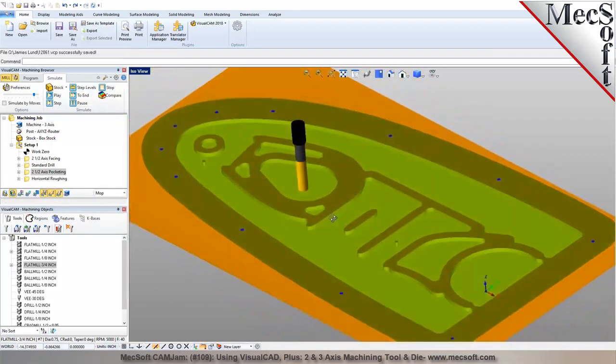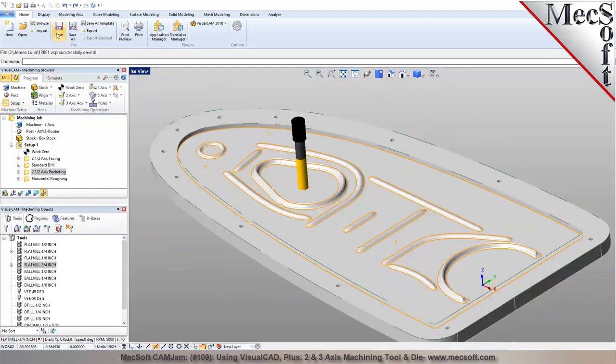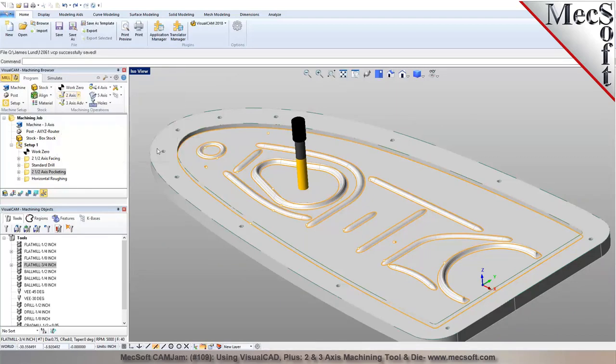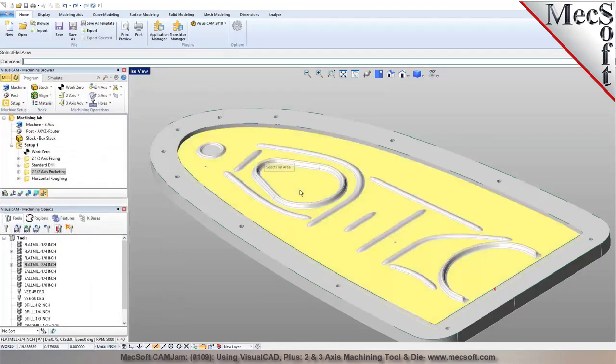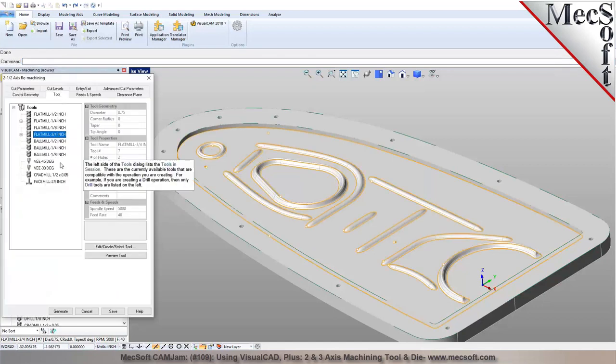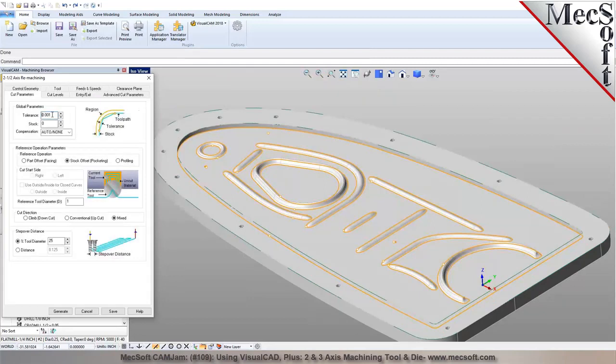Now you are noticing that there are some areas where the tool was unable to machine those pockets. Now for those areas, with the Pro, you can use this method called 2-axis remachining over here, and I can select the same set of boundaries. So in this example, I'm just using flat areas. I could have extracted some curves as well. Now I can go from a 3/4 inch to maybe a 1/4 inch tool, to clean up some of those tighter areas. And then use the same type of parameters in here.